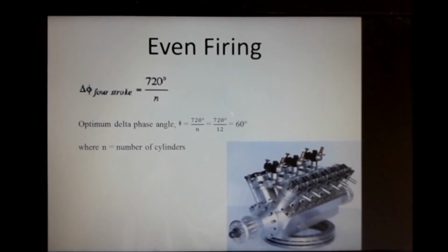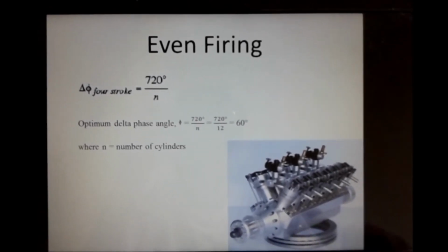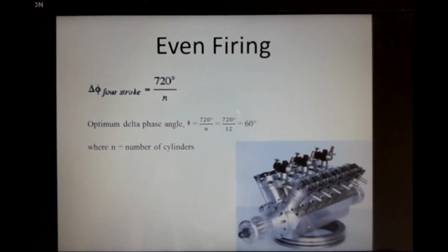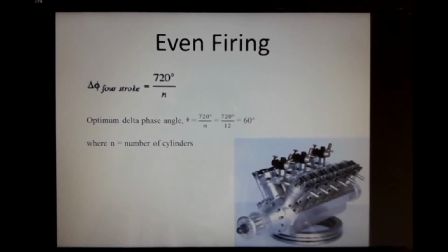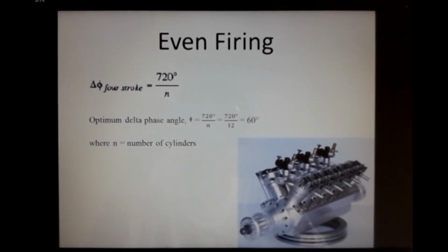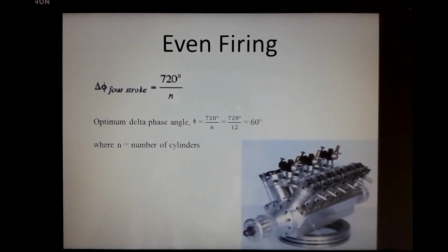First of all, what is even firing? From the name itself, we can understand that it is firing done evenly. In more technical words, it is power pulses evenly spaced in time. But how much is it spaced? That will depend on the number of strokes and also the number of cylinders.